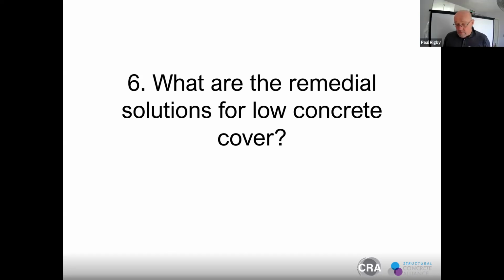Yeah, an effective product for that is probably the use of a fairing coat. And the beauty of fairing coats, you can use them in new build and refurbishment. And for those who are not familiar with the term fairing coat, it's basically a cementitious skim, a sort of smoothing compound, which is generally applied at 2 to 3 millimeters and has been accepted by the industry for many, many years. That will give you theoretically 20 mil of extra cover. So if you double that up, you can very quickly get to a 40 mil sort of cover.